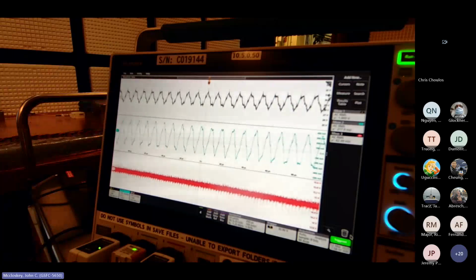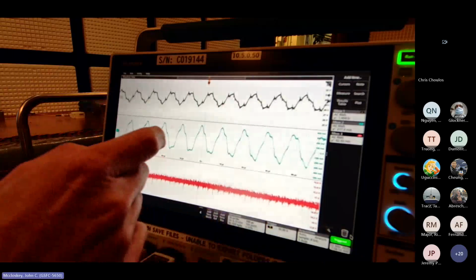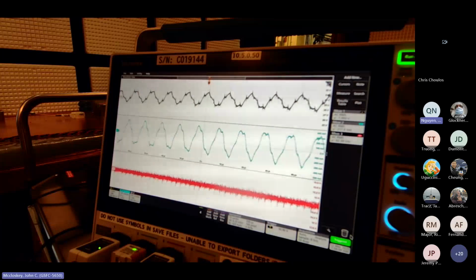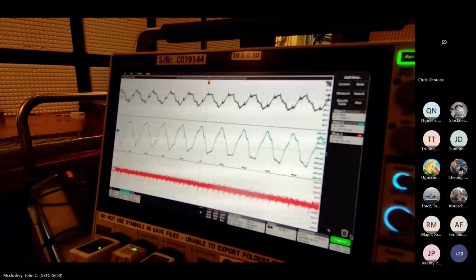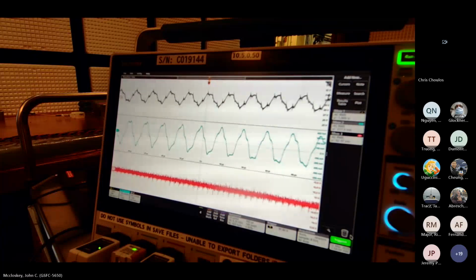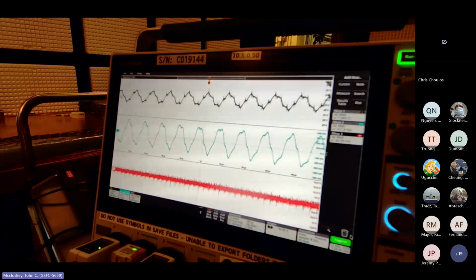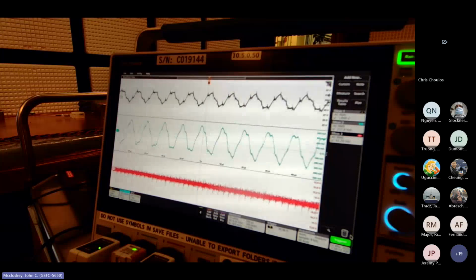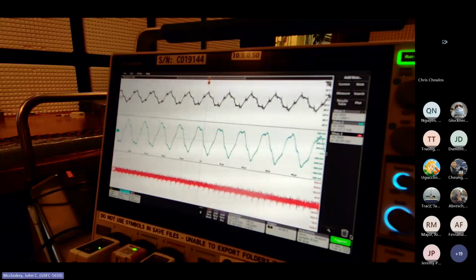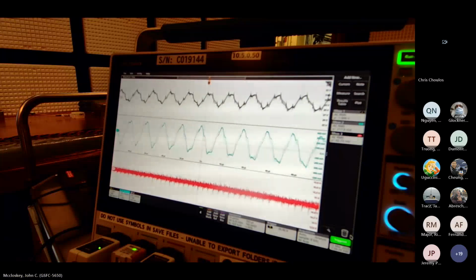It's a very ugly waveform, right? But now let me write the numbers down and then I'll comment. So now our current is up at about 217 milliamps. Current's gone up almost an order of magnitude. Okay, so we're getting into the realm where the input impedance is going down. Right, we're at 100 kilohertz with a switching frequency of 400 kilohertz. That's not real surprising when you get up in that zone of the switching frequency of the power converter.